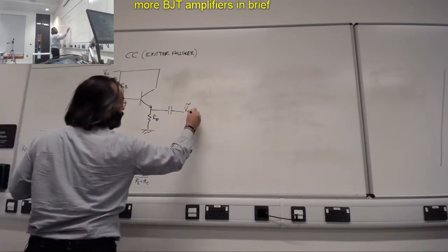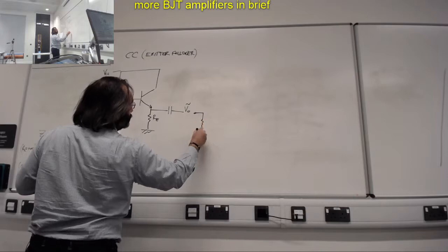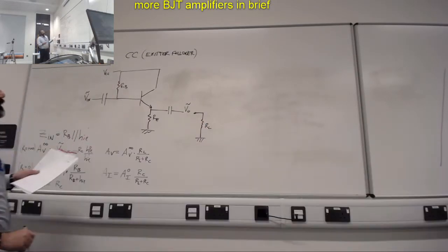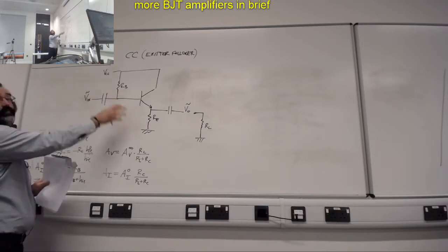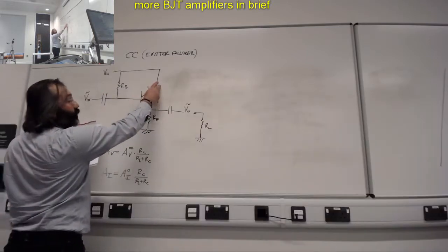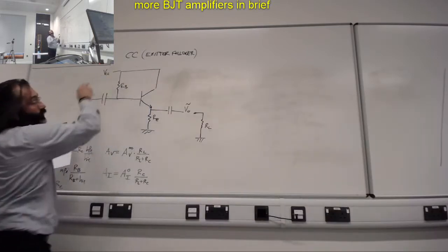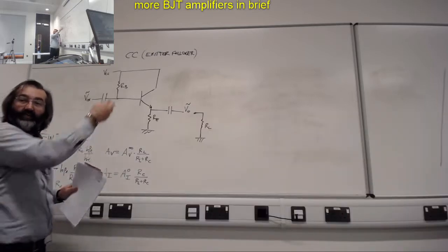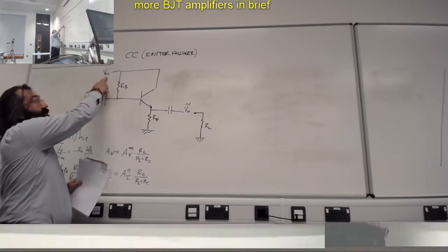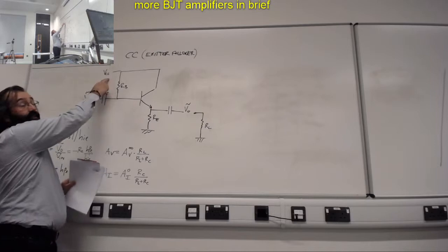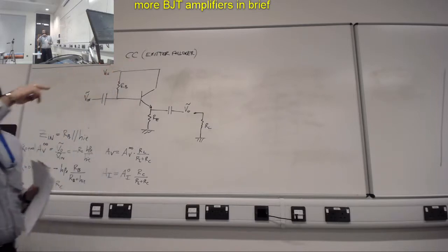And obviously, in case you wanted to connect a load, your load would be here. So this is extremely simple. Two resistors and the capacitors and the BJT. And you see the collector is connected straight to the power supply, the DC supply. When we do the AC analysis of this, this must be effectively grounded. And so the fact that the collector is grounded, that's why it's called common collector configuration.